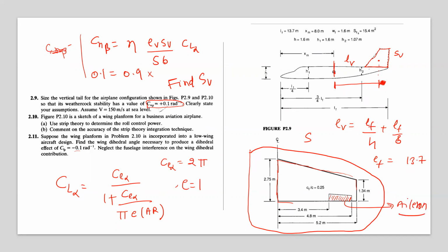Sometimes what happens is that you've chosen some aileron from somewhere, I don't know how, but then you don't know how its impact will be. Whenever you formulate the control laws that will dictate the aileron angle for different kinds of maneuvers, they will require the effect of deflecting the aileron by a certain magnitude, and what happens to the airplane motion. So you need that derivative, and that derivative is known as roll control power.